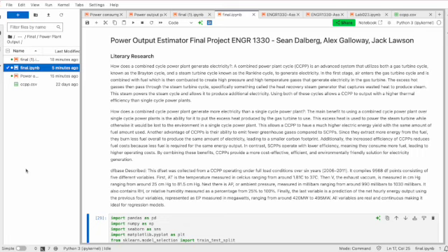And how does it do this? The main benefit to a combined cycle power plant is that it can put the excess heat that would normally be wasted in a single cycle power plant to use. It is used to power the steam turbine, while otherwise it would be lost to the environment in a single cycle power plant. This allows the CCPP to have a much higher electric energy yield with the same amount of fuel being used.